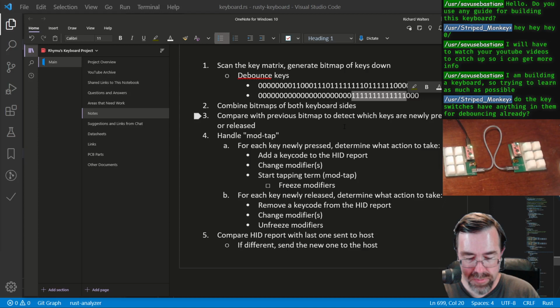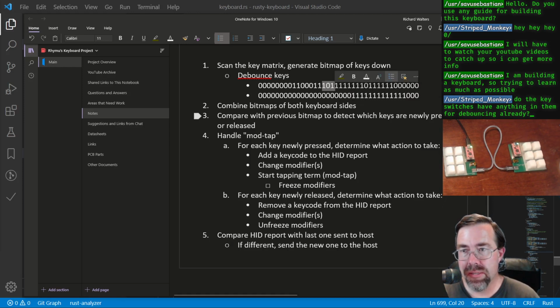But what I've seen experimentally is there's still some electrical bouncing. So there's physical bouncing where, when you pass the point from going from a 0 to 1, it might vibrate slightly right on that edge, and you might see something like this.